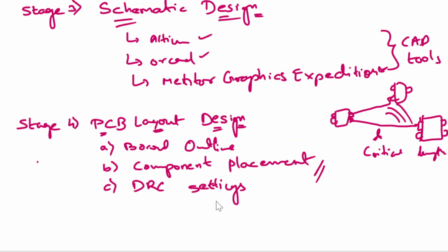The next action in this stage 4 is that you need to do PCB stack up. Now you are aware of the complexity of your circuit design, so you may have to sit closely with your PCB layout engineer, or with experience you will come to know how many layers you can route this much complexity of board or circuit in. Maybe you want to shield them, and I'll explain what shielding is going forward. So you may require some extra ground layers or extra power planes. Based on those requirements, you have to arrange the PCB stack up.